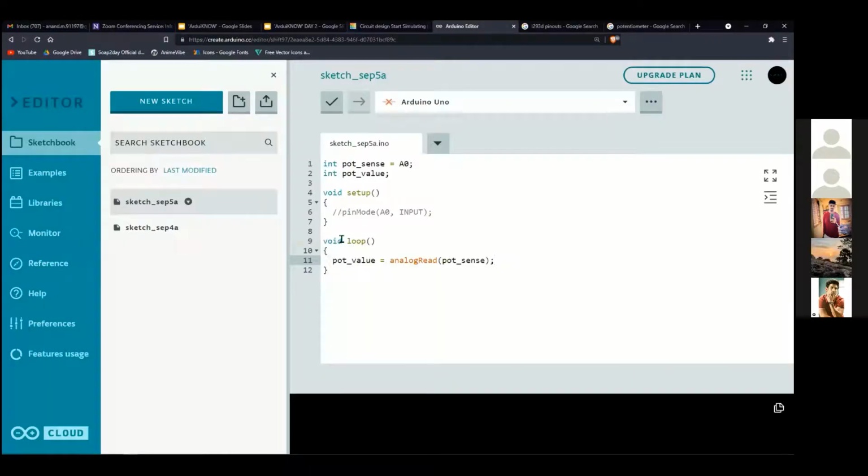In order to enable the serial monitor feature in your Arduino, there are some certain keywords that you need to include in your main code. We need to have some setup, since we want to have data transferred to a serial monitor. There is a particular keyword called Serial.begin. This is the keyword which is used to initiate the serial monitor feature in your controller.